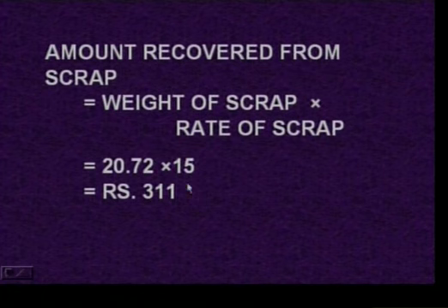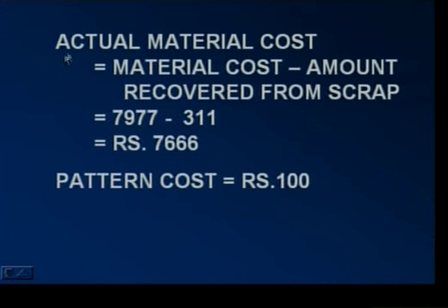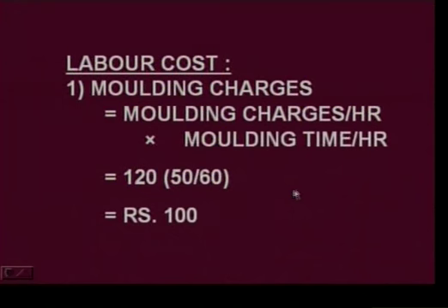7,977 rupees. Amount recovered from scrap, weight of scrap into rate of scrap. So, the value becomes 311 rupees. Actual material cost is material cost minus amount recovered from scrap. 7,977 minus 311, the value becomes 7,666 rupees. The pattern cost he has given as 100 rupees.